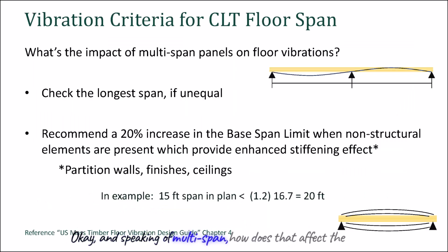Okay, and speaking of multi-span, how does that affect the vibration performance we just talked about? Does having multiple spans help with the bouncy feeling? That's a great question. And yes, it often does. Here's another fascinating insight. For multi-span CLT panels, especially continuous ones, designers can often recommend or justify a 20% increase in that base span limit we discussed earlier. A 20% longer span for the same vibration performance?